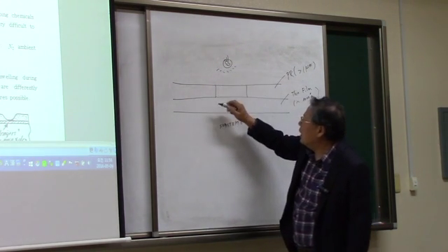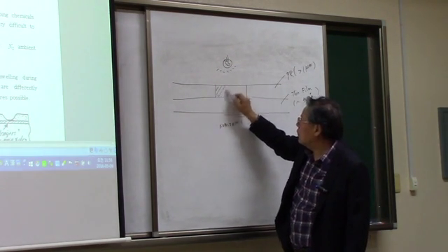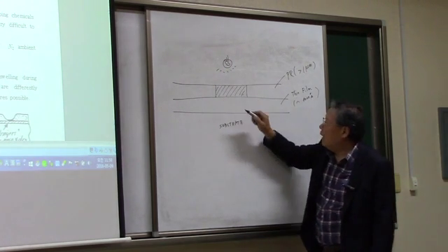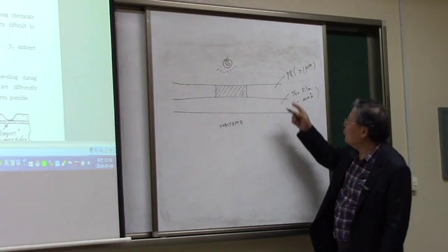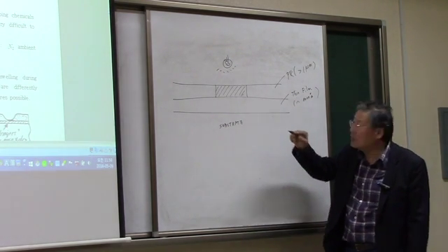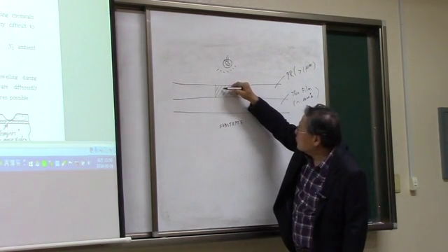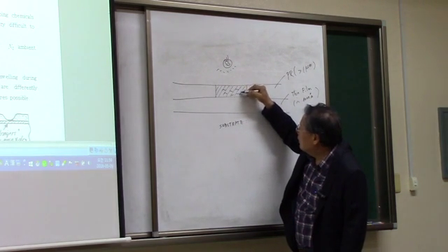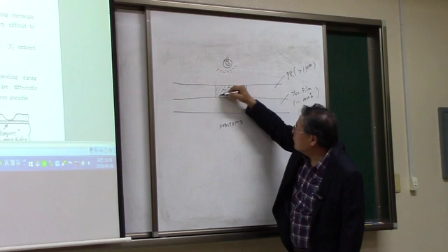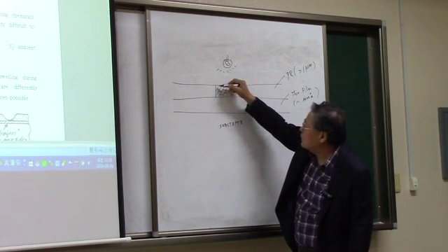Now, with the mask, let's suppose you have some part exposed to the light, and this part exposed to the light, and the other part not exposed to the light. Then if you use a negative photoresist, you're going to have a cross-linking of all this part with the promoters. Okay, it becomes heavy molecules.